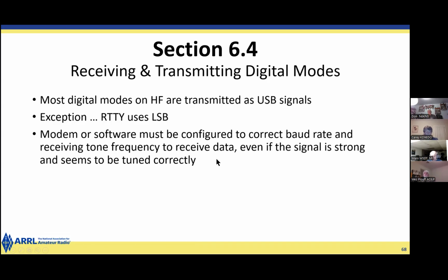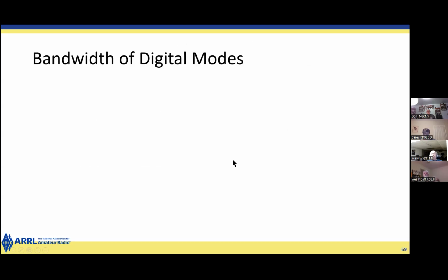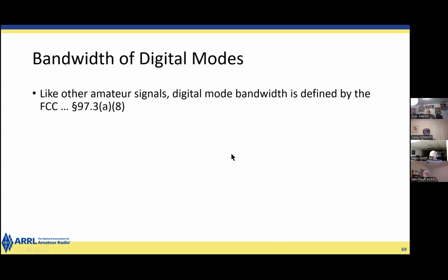So you have to configure your modem, or more likely your digital mode software, to the correct baud rate and the correct tone frequency, and your radio has to be listening on the proper sideband. And all these things have to be correct, even if you're hearing a strong signal. Otherwise, you'll see gibberish decoded, or else you won't receive the signal at all. Or rather, you won't decode the signal at all.